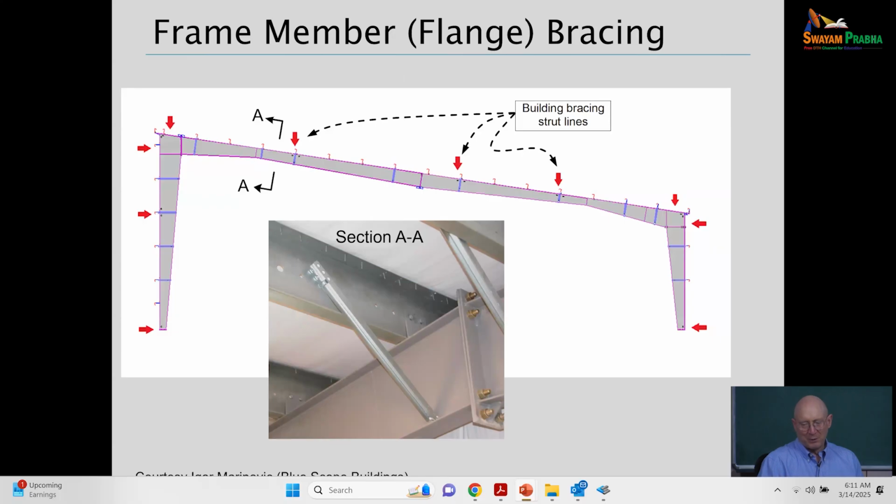And here's a graphical illustration on a representative metal building frame. So you can see these various locations where we have girts and purlins. They're attached to the outside flanges. If we zero in on a location like section AA, we see clip attachments of the top flange to what looks like a Z-type cross-section for the purlin there.